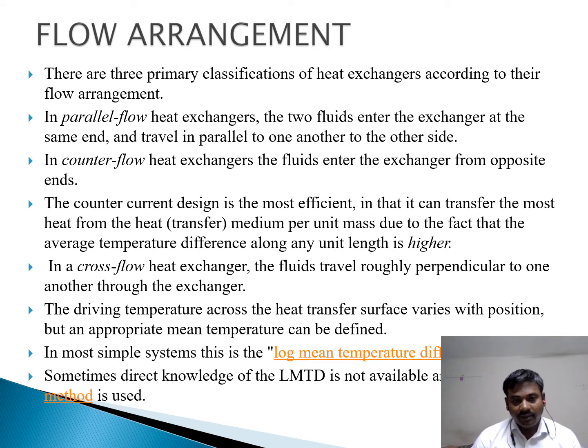Then, when we go for the heat exchanger, the main parameter is the flow arrangement. We have three types of flow, classified as parallel flow, counter flow, and cross flow. In a parallel flow, the hot fluid and the cold fluid enter in the same direction, while in counter flow, the hot fluid and the cold fluid flow in opposite directions. And in the cross flow, the hot fluid and cold fluid flow in perpendicular directions.